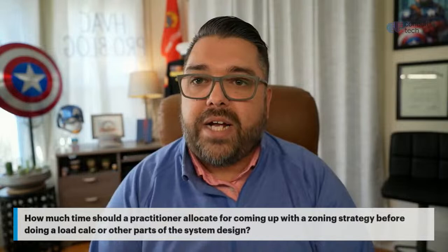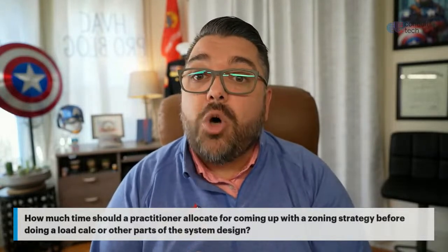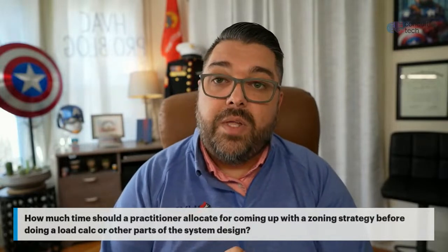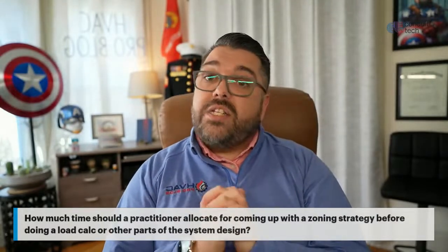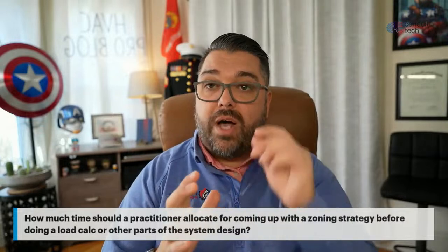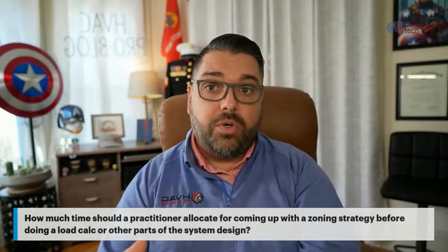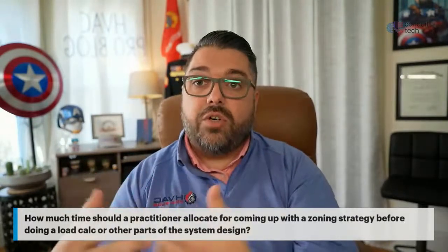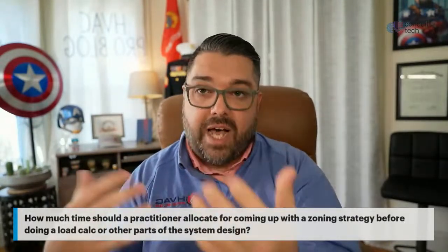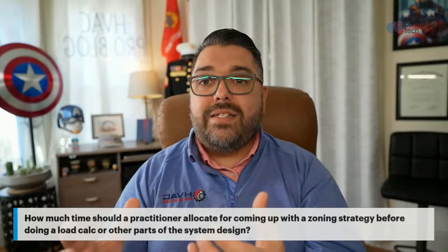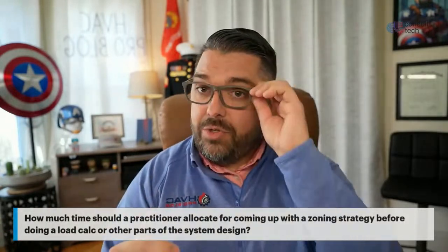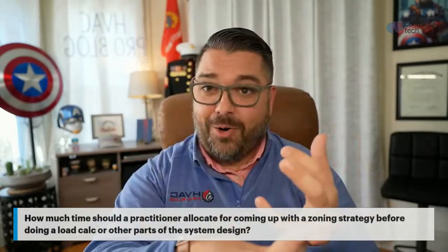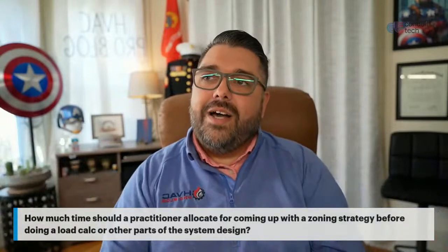How much time should a practitioner allocate for coming up with a zoning strategy before doing a load calc or other parts of the system design? All right, so this is an art, and this goes to how you're going to question the homeowner and pull that information out. So hopefully you have a good site survey process and comfort design process. And you have to do this at the house, right? So, you're not going to be able to come up with a zoning plan without talking to the homeowner or visiting the home or looking at a set of plans, right?